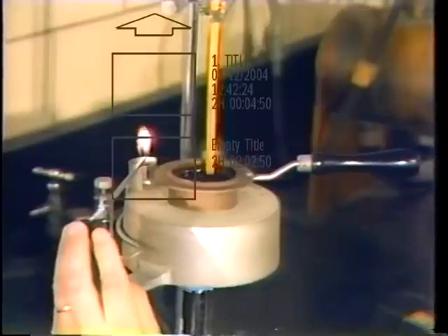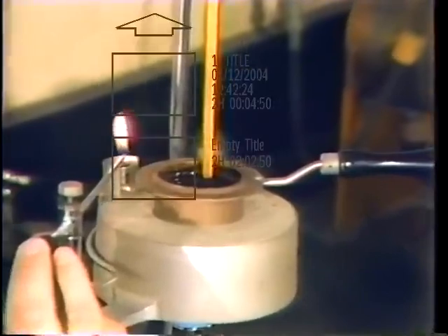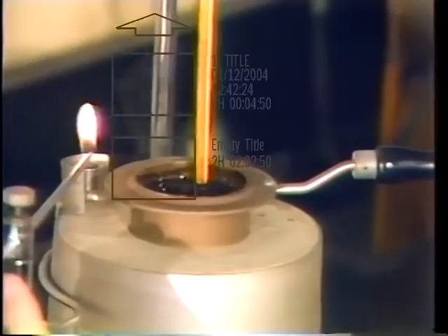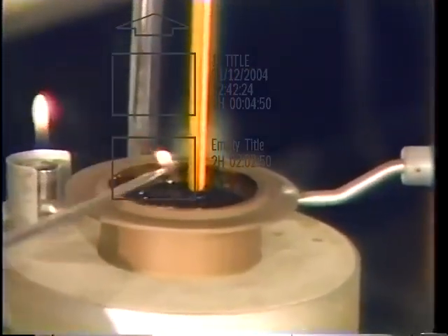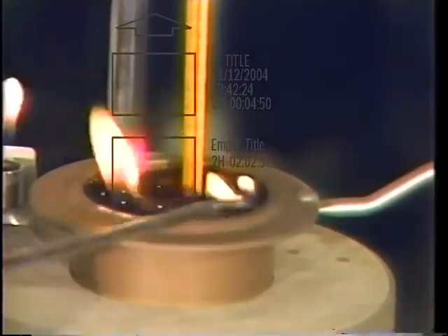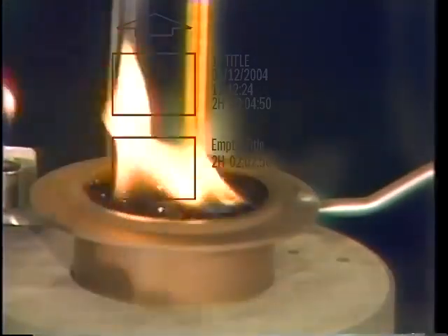Fire point is the slightly higher temperature at which the lubricant will burn steadily when exposed to a flame. This occurs because enough vapor is created to cause continued burning. Both flash point and fire point are important to know for safety reasons. If flash point and fire point are exceeded, a fire hazard exists.